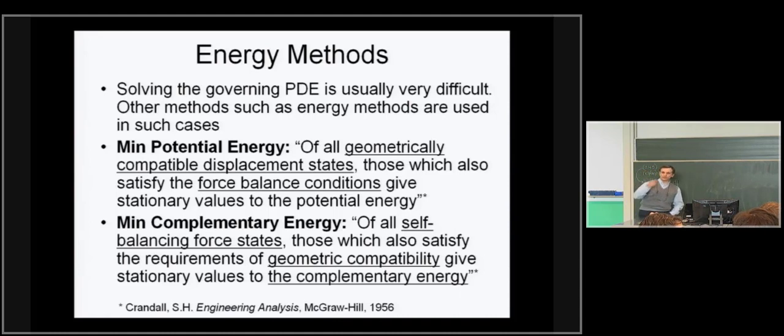That means any boundary conditions on displacements. You don't do anything about boundary conditions on the forces. Then you choose to satisfy your equilibrium equations approximately, which means you will minimize the energy. And if you minimize the energy, the result will, on the average or in an approximate way, satisfy your equilibrium equations. So, equilibrium equations, strain displacement equations, stress strain equations. Of those, I pick the strain displacement equations or the strain compatibility to be satisfied exactly. And then I will satisfy my equilibrium equations approximately if I minimize the energy. Now you might say, what happens to the stress strain equations?